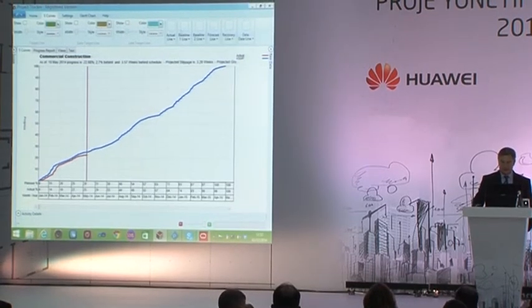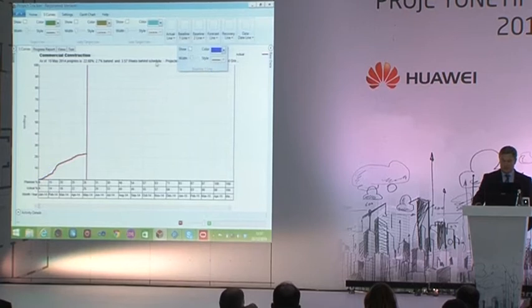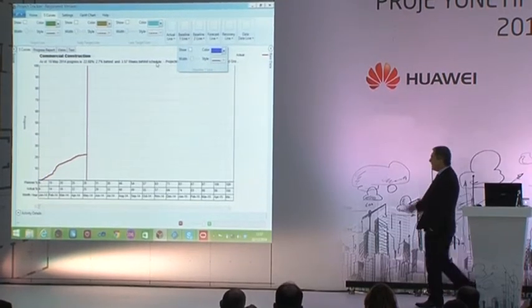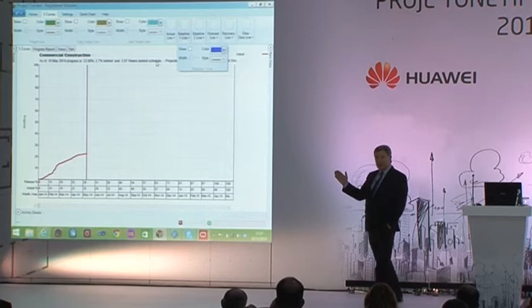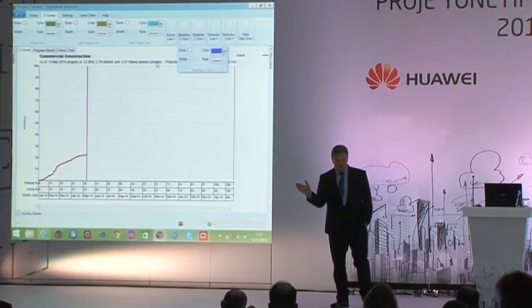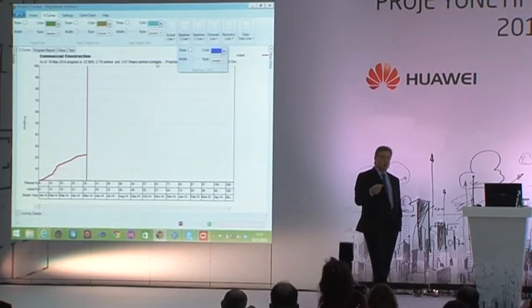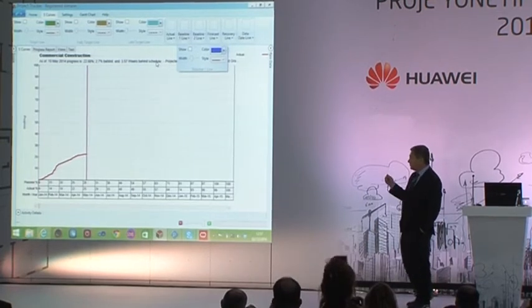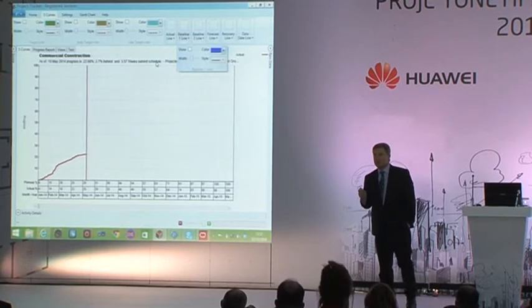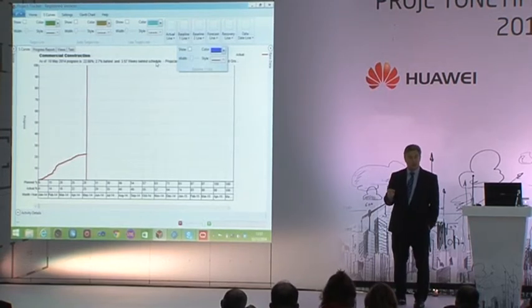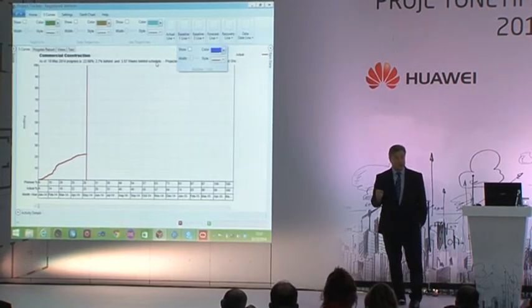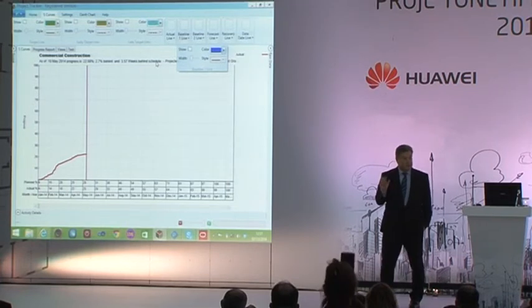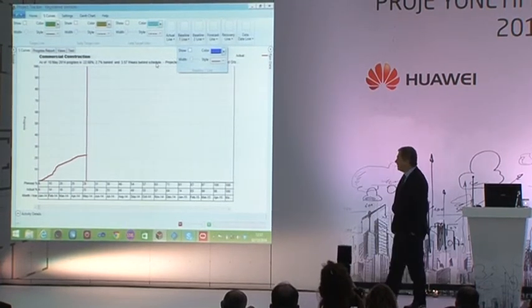So I can turn off these curves, and I'm just going to turn off a couple of them. The first thing we've got is our actual line, and that's the actual amount of duration we've completed. I said to you, you don't need to import costs or resources. You can do that, and I can show you that type of curve. But one of the simplest curves, the way of monitoring progress, is just monitoring the duration that we've done. So it's 5 days, accumulates to 5 days in the graph.